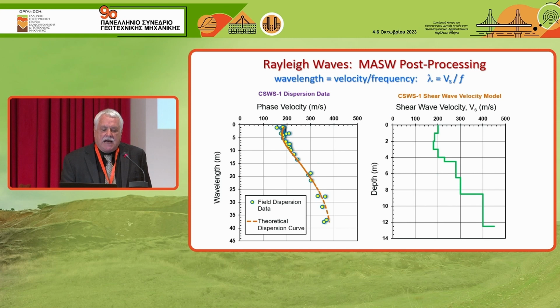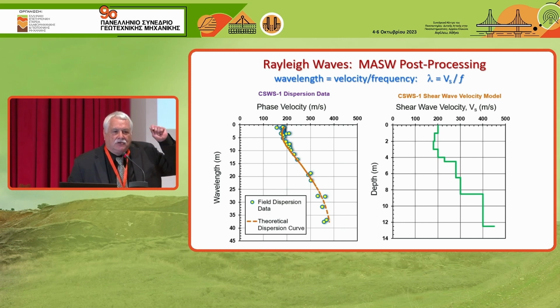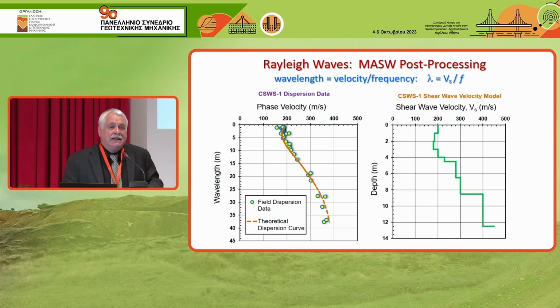And they end up with some dots that look like this. The dots are on the left-hand side, and they sort of develop a model. It's funny to set up 24 geophones. That takes about 20 minutes. And then they take literally a sledgehammer or a drop hammer in this case, and in less than 1 second, that's the event. All the data are collected in 1 second. It takes longer just to set up the geophones because most of them are wired. Although at Georgia Tech, we did purchase a wireless system, so you can have 24 wireless geophones. The setup's much faster.